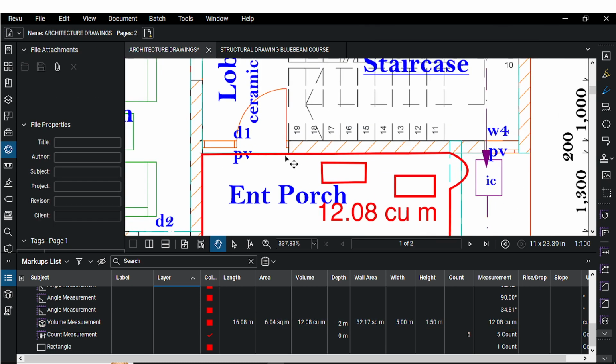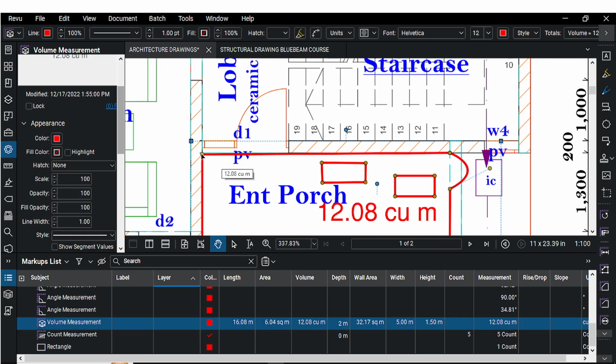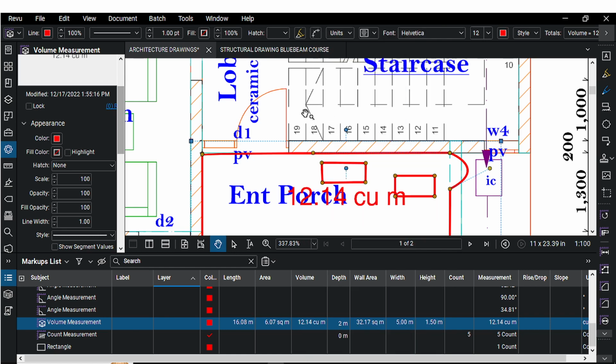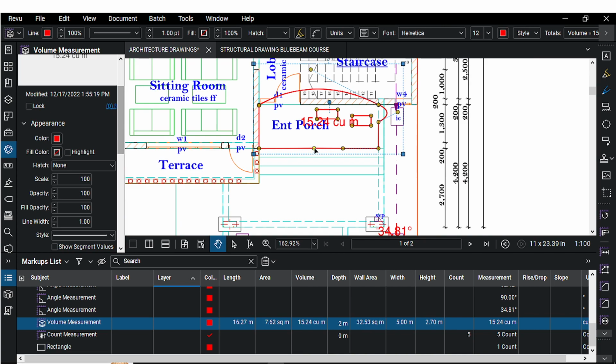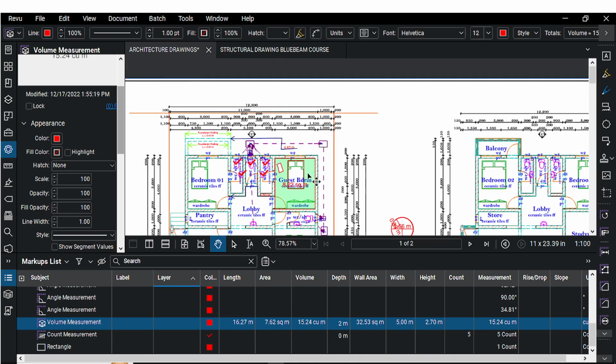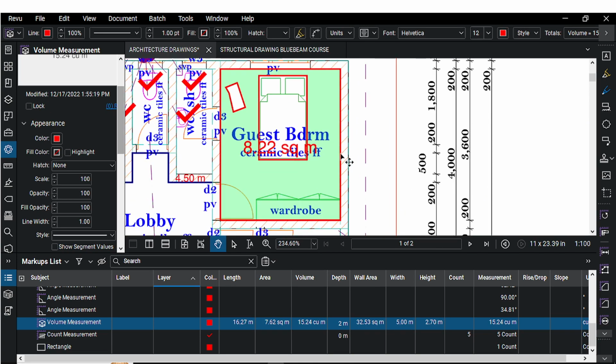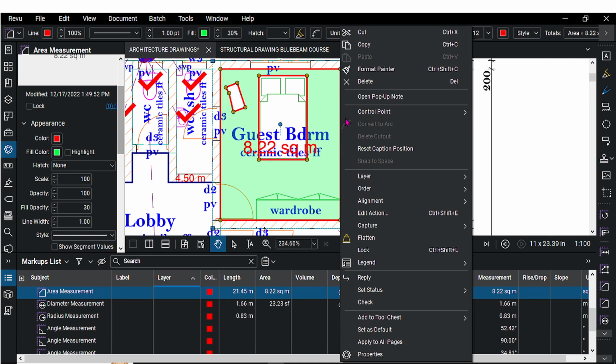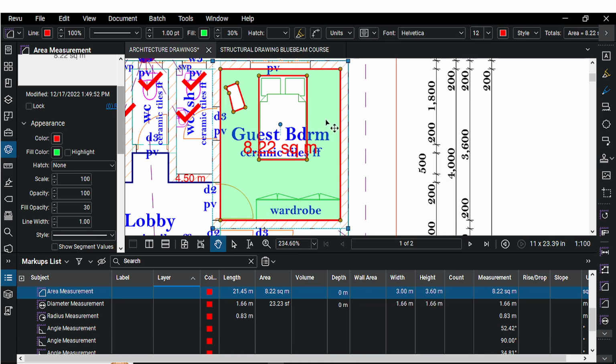Yeah, so let's repeat again. Let's say, for example, I want to convert this particular line to curve. I'll just right click and click on convert to curve. It's possible to convert to curve like that. So those are the options that we have. You can as well do so to this one. So I can click to select it and then proceed to the boundaries here. Right click. Sometimes you find that we don't have convert to curve active, so try again.